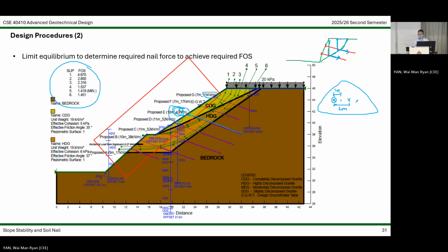Okay? Many design engineers, when they first do their design calculation on slope, will make this mistake, because they will simply extract the value from the two-dimensional SLOPE/W analysis into the spreadsheet and then check all the internal stability. This is incorrect.